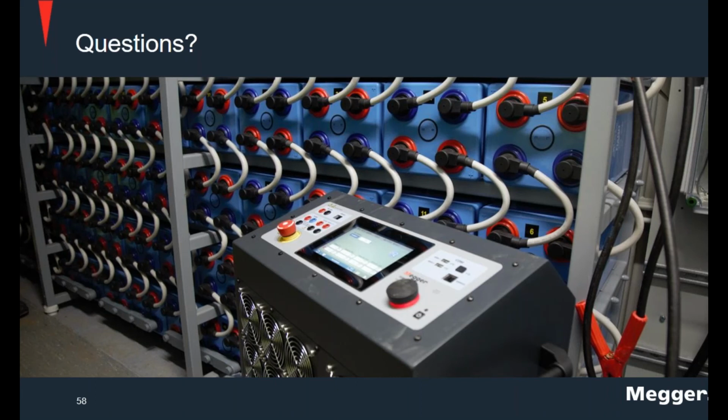All right, thanks, Sanket. Daniel, next question's for you. What kind of equipment or tools do you need for this type of testing? Okay, good question. Apart from obviously the instruments that Bonnie touched upon, the discharge unit, in our case, the topple, and the individual cell monitors, the DVMs. When you talk about the tools, everything you need to, for example, jump out a cell, right? Bonnie did cover this in his presentation. You need to be ready to jump out any cell that you identify with the DVMs to be weak before the end of the test.